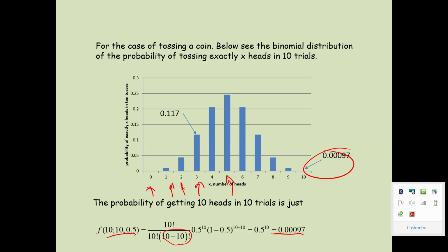In that case, each year is one trial. What's the probability that you'll get, let's say, 3 100-year floods within a 50-year period? That's an important question when it comes to designing infrastructure. The same kind of question could also be asked for industrial applications.